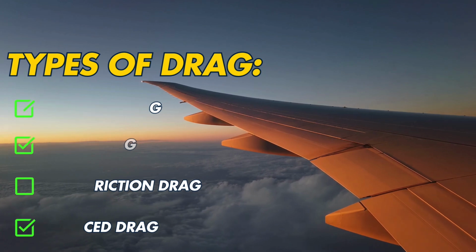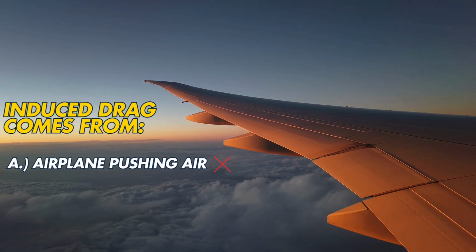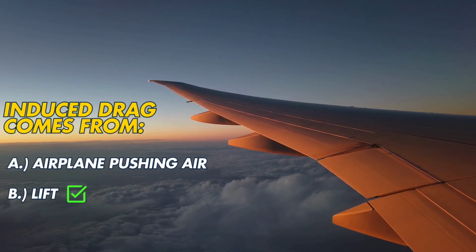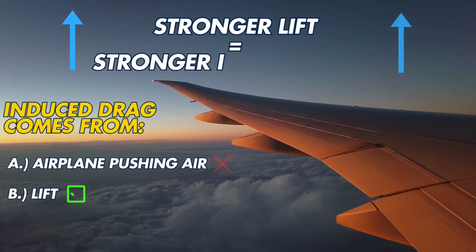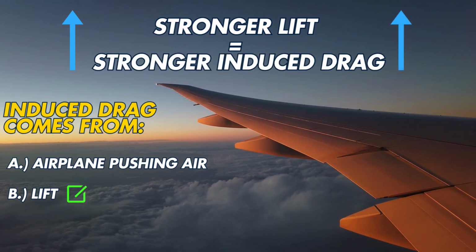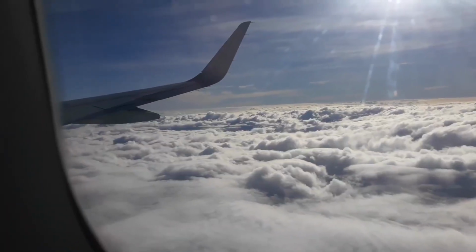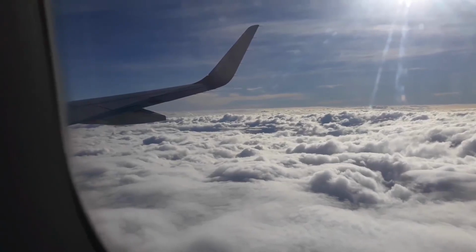Induced drag is unique. It doesn't come from the airplane pushing through air. It comes from the very thing that keeps the airplane in the sky, lift. Yes, the act of generating lift creates drag. This is one of the great paradoxes of flight. The stronger the lift, the stronger the induced drag. So right away, engineers are dealing with a trade-off. You need lift to fly, but lift itself creates inefficiency. And this inefficiency becomes most intense at one specific location, the wingtip.